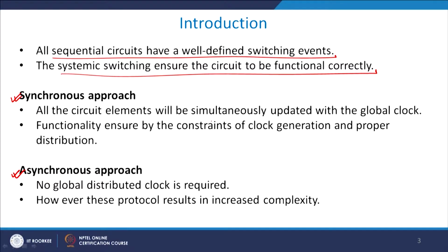In this case, as I told you, all the circuit elements will be simultaneously updated with the global clock, which means that there will be a global clock driving all the digital blocks within the system. Assuming the global clock is run in such a manner that the time at which it goes from 0 to 1, the rising edge of the clock, is exactly the same in all the blocks, then we will accept that in all the blocks the data will be inserted at the rising edge.